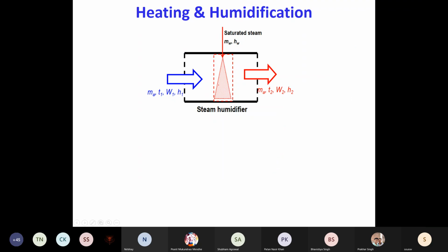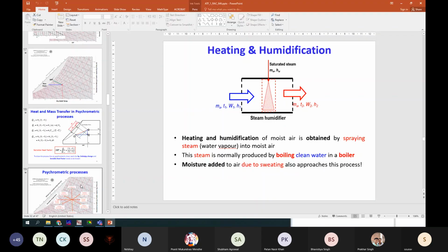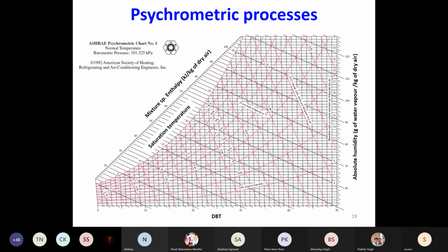Let's mark the incoming point. So 42 degree, draw a line, and 18-degree WBT. So your WBTs are marked over here, 10, 15, 20 like this. So this is the dotted line for WBT, 15, 16, 17, 18, 19, 20.